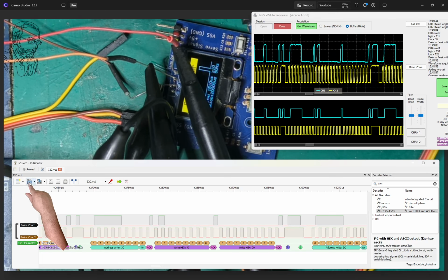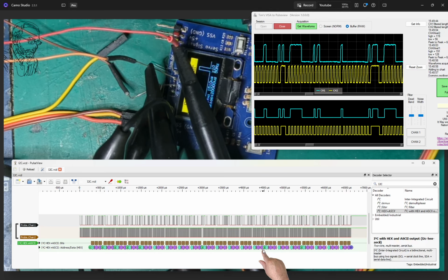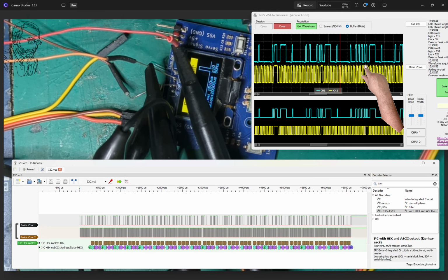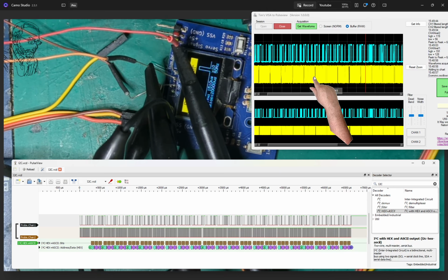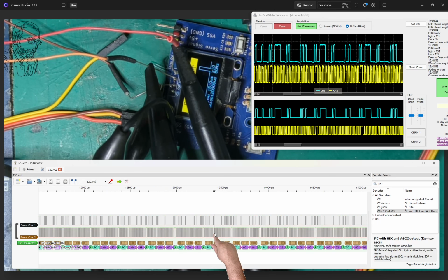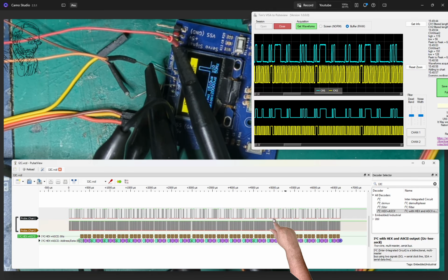Now you notice that I keep going to file and what have you, but if we're going to keep it on I2C, like I say, you can just see that all the data's here. So all this data, wherever we look, we've got separate commands and data addresses filtered out, and that's what we've got here. So you can see that this is quite a bit of data we can capture with my oscilloscope.